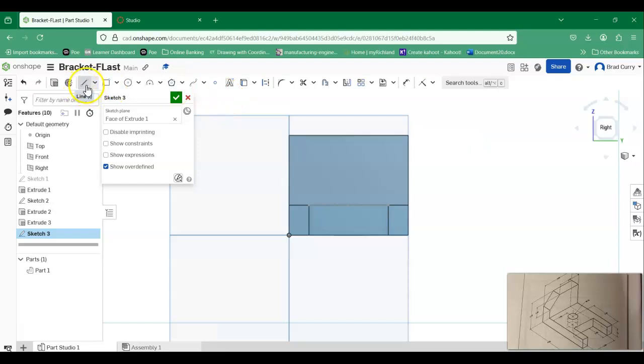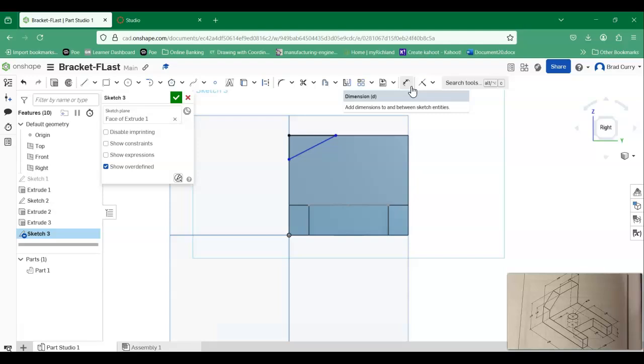Now, at this point, I'm just more or less drawing lines, and we know it's going to be a triangle, so again, I don't have to worry about where I place this. You do need to make sure that you're not hitting some of the constraints. So notice like a midpoint. There are other constraints that might be in here. So make sure that you're not catching one of those other constraints. So, and close off. So there is my triangle. So I've got that in position.